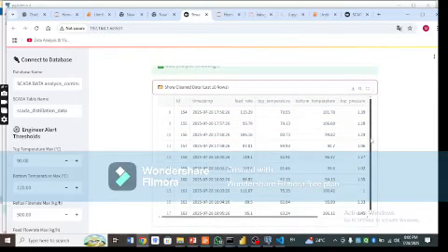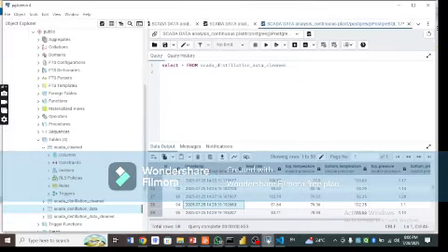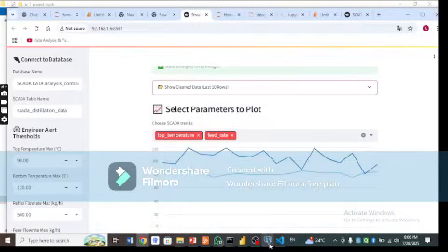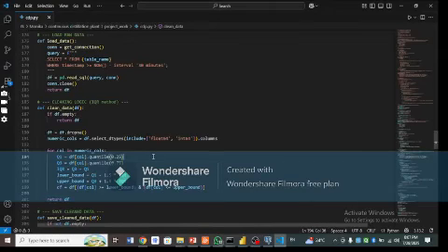But in the real world, data is not always perfect. We observe that around 2 to 3% of the readings are missing in the SCADA system due to sensor failure, signal loss, or connection delays. We handle these by automatically cleaning the data every minute. Any missing values are safely removed, and outliers like sudden temperature spikes are detected using the IQR method. Everything is automated yet safe for the plant operation.